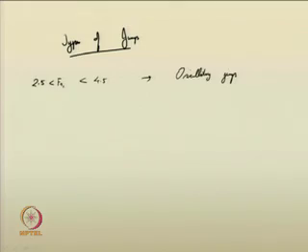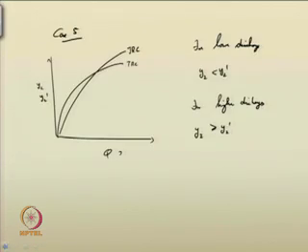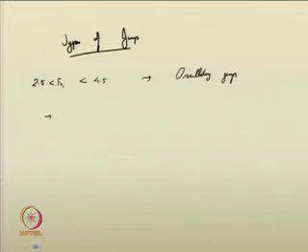Also, you need to understand that the tailwater depth, as in the last two cases, is quite essential, that is, your jump depends on the tailwater depth. So, how much tailwater depth you are providing is quite significant. Based on that, the type of jumps will also vary.